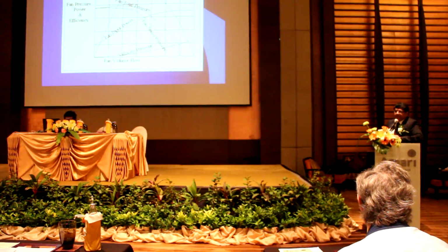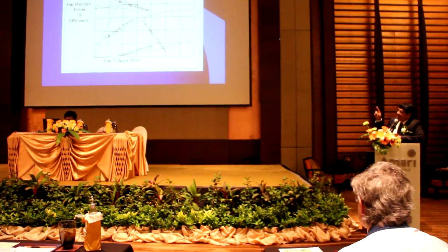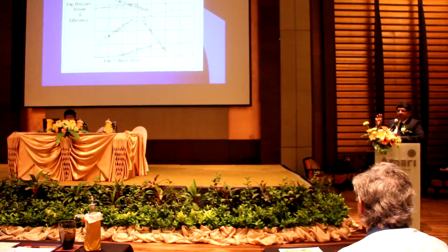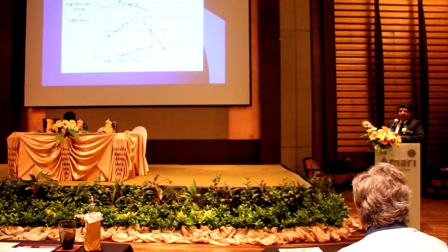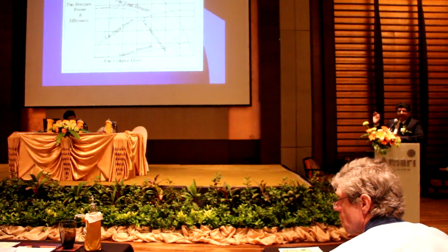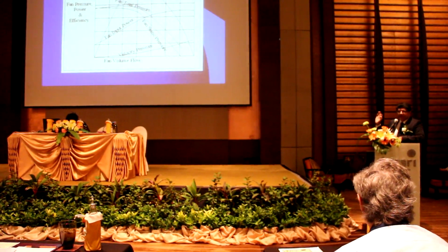So most of the people give these curves, but then finally at the end when you're in the plant, you're not able to measure some of the things like static pressure, because in situ measurement of static pressure is very difficult. What you can do in situ, somewhat accurately within the permissible inaccuracies of field measurements, is the airflow from the fan. That's the best you can do.